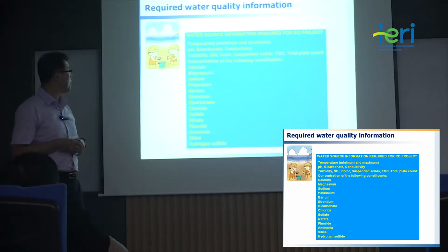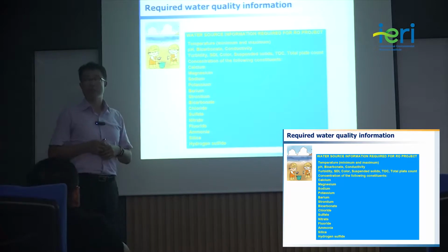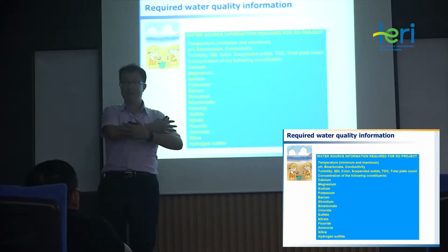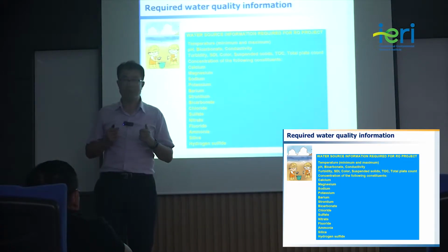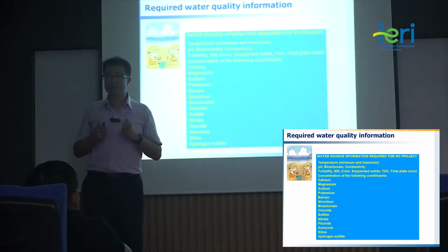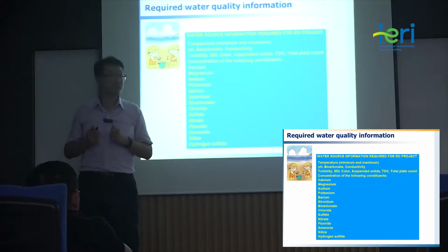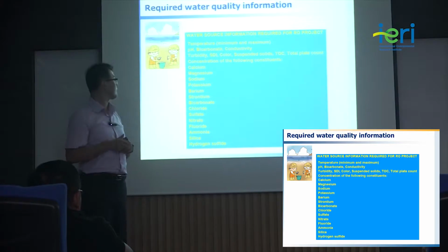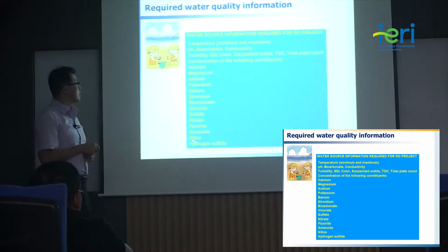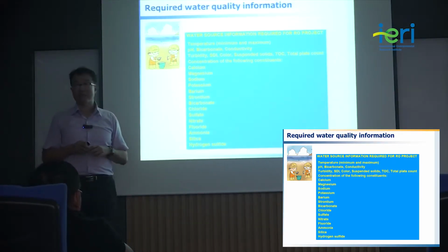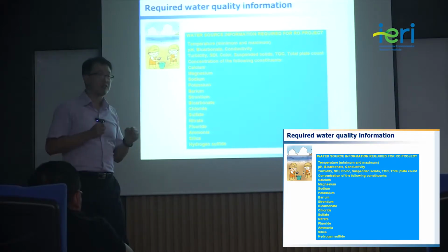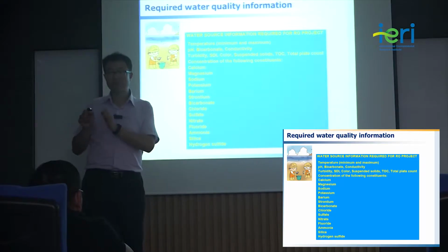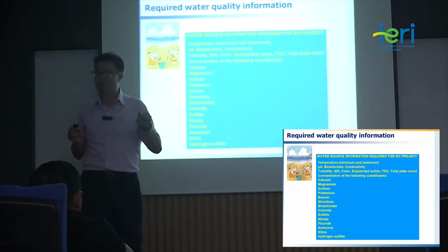So for example, if you have high turbidity, you need to put more media filters in series, or you may think about putting in a membrane-based pretreatment system like microfiltration or ultrafiltration. If you know the water quality of the seawater very well, you can design the system. Membranes are used not only for reverse osmosis, but also for pretreatment.